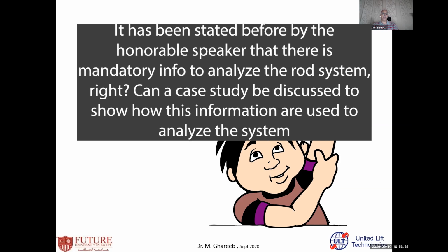Because you design your well to produce clean fluids, only oils, and with time you find, for example, some problem, some pumps sticking, and the fluids, you know, just what we produce, sand starts to come out of solution, and sand starts to come with the fluid. Then sand, in this case, is very important. You need to have your fluid properties. You need to have your current well testing. You need to have your well inflow performance.